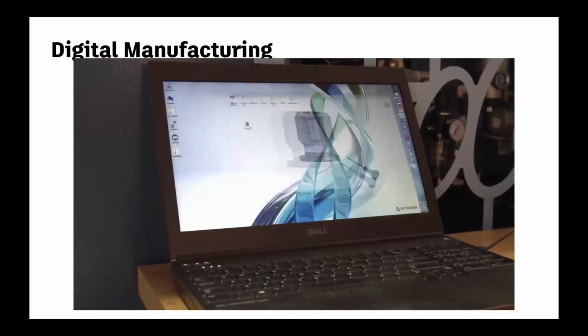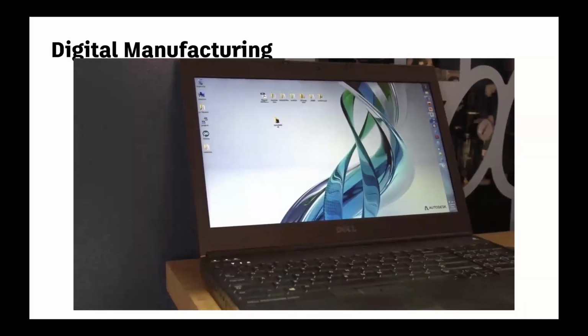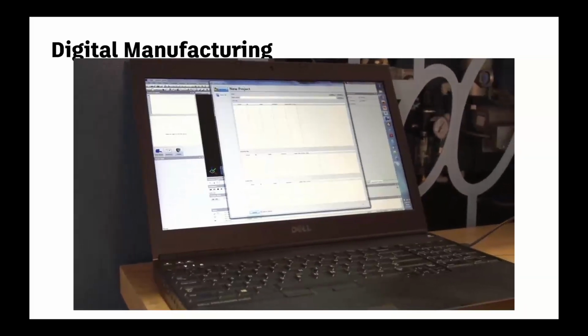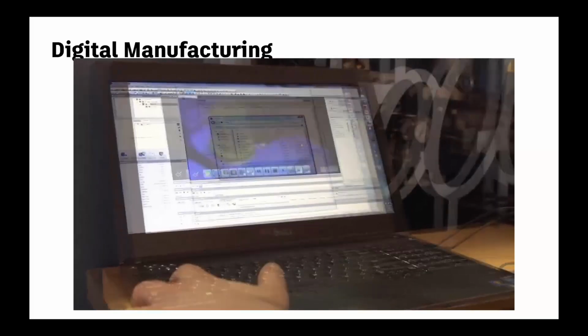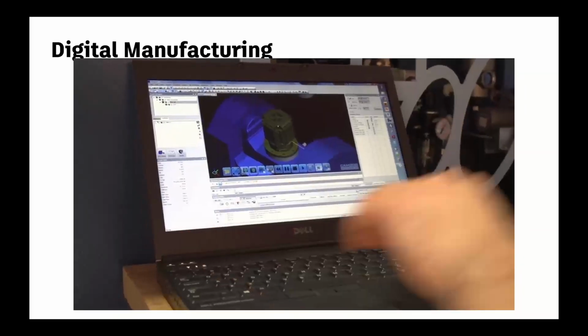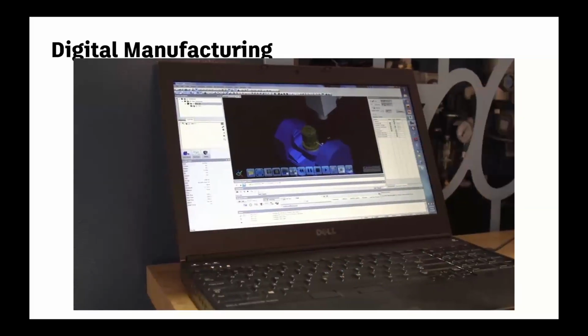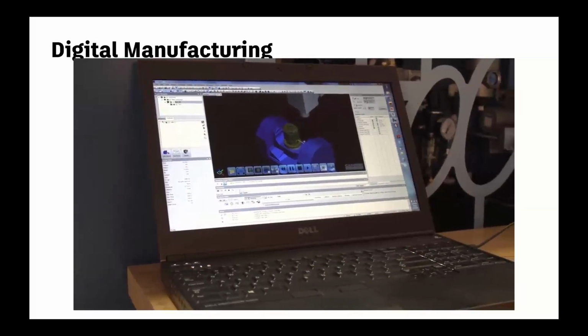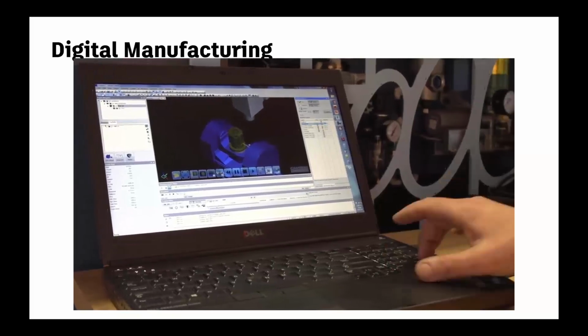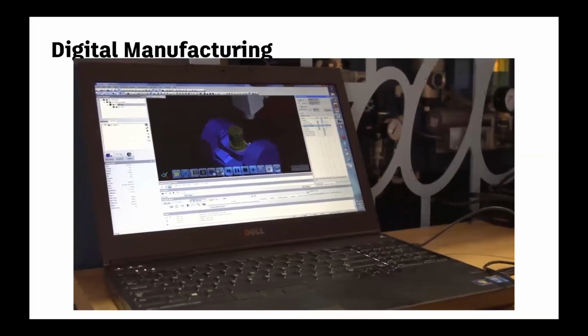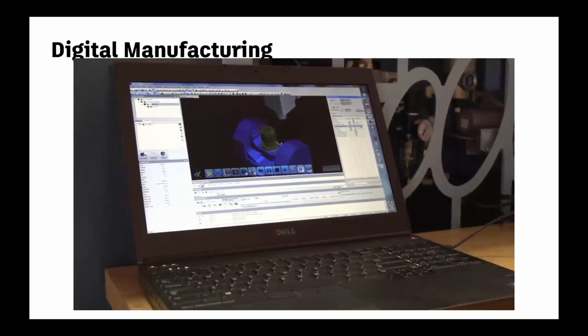It's simply drilling a coolant hole through the tombstone to be able to drain the coolant out of it. So from a machining perspective, this is a very simple operation. Simply drilling, push the drill into the material, remove the drill, and that's really the end of the operation. So as far as the CAM system is concerned, it is a very simple motion, very simple movement for the machine.